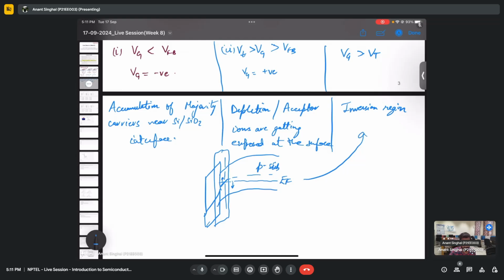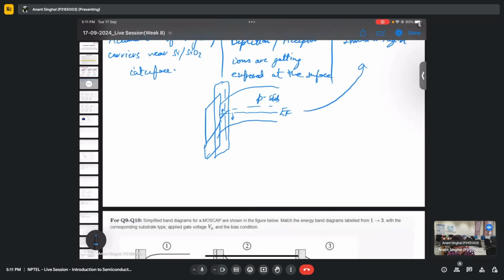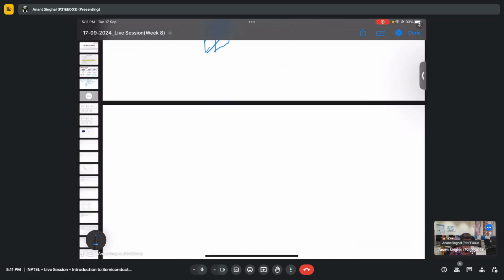So this was the very basic that we already covered in the last lecture, and this week we'll be covering the first concept, that is, what is this threshold voltage. I am naming this as Vt in all the cases you can see. So what is this threshold voltage and how do we calculate it? I guess we know what threshold voltage is as of now. It is a voltage at which the surface potential becomes twice the Fermi potential. We were getting the inversion, and this particular voltage is nothing but the threshold voltage at which this happens. And we saw in the CV plots also.